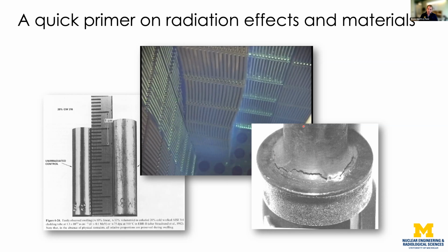that sits outside these fuel elements, where the radiation has effectively totally embrittled that material and made it so when you have a stress component applied, you get this cracking. It's called radiation-assisted stress corrosion cracking along this baffle bolt. You would imagine a cracked bolt means that it can't carry load anymore, so it's not doing its functional component